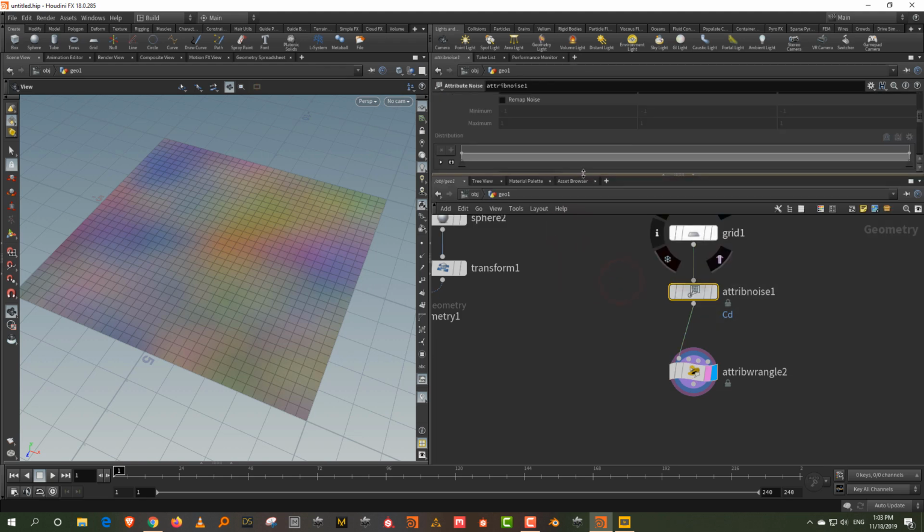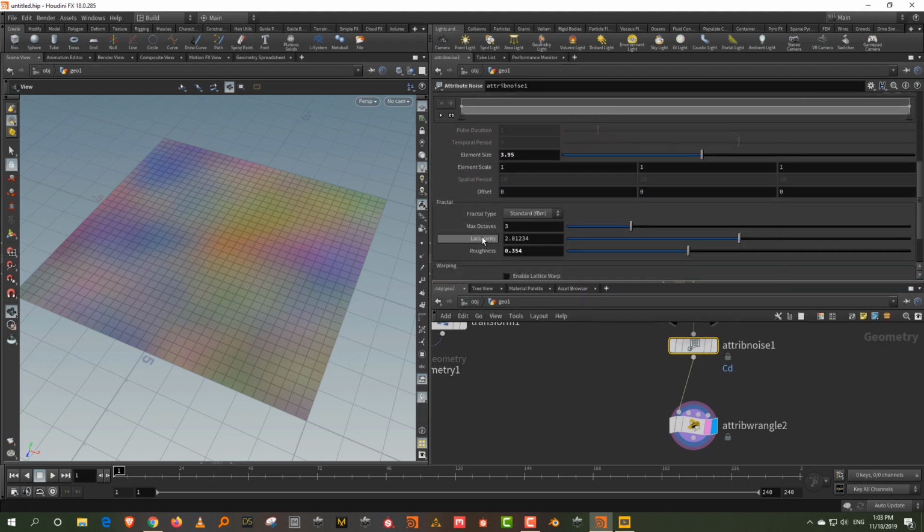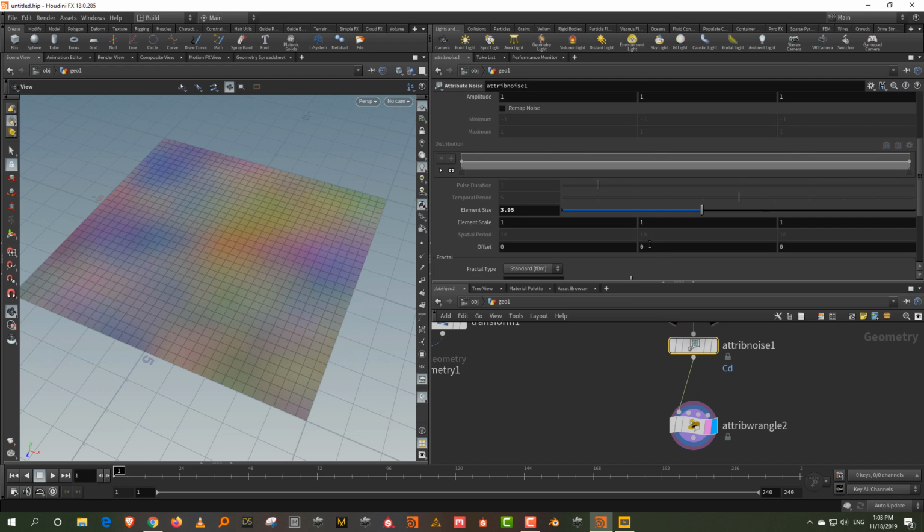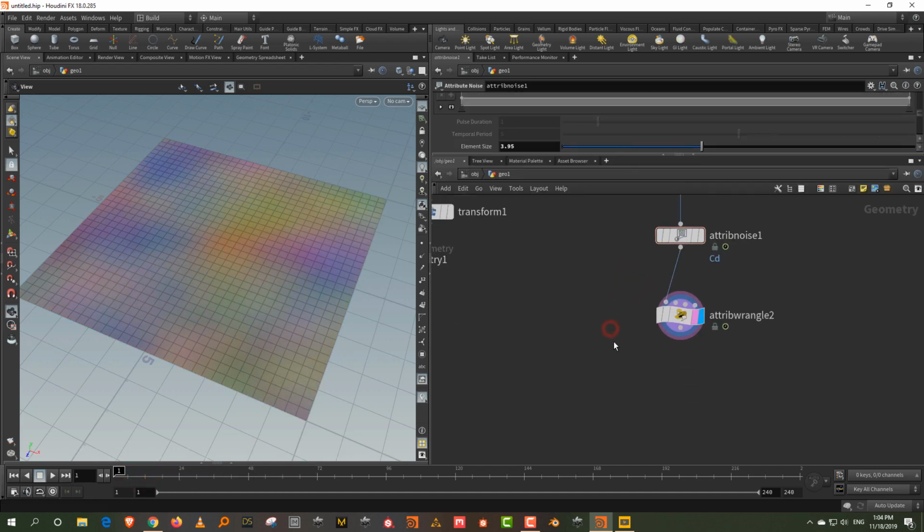And let's also do one thing. Let's take the noise and we will animate this. The simplest way to animate is you can take the offset value and just animate it. So I'll come into the y offset and put in @Time. So you should have an animated noise map. Okay, pretty simple. Now let's take a poly extrude.